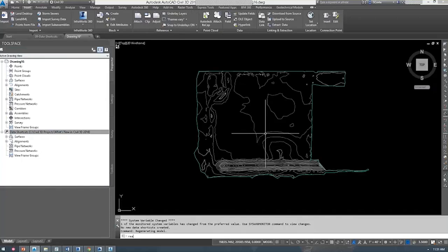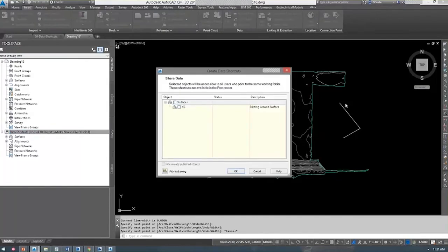And you can now do other things. Let's just draw a quick polyline, and you can create the reference without now needing an additional save. So if you remember before in earlier versions of Civil 3D, even if you just panned and zoom extended, even if the drawing was saved, it would make you save again before adding the data. Now you can add it directly without that save.